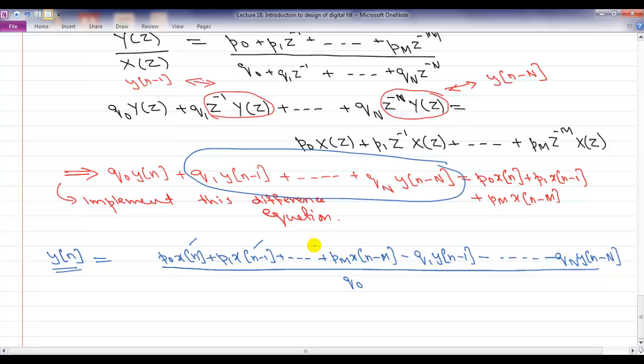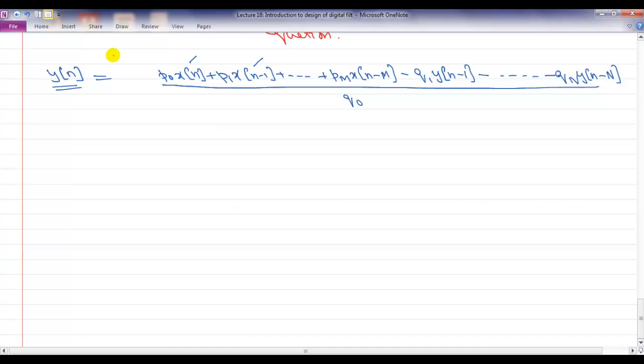So anytime you are given an IIR filter, you cannot implement it directly in hardware, but if an IIR filter has a z transform which is a rational function of z, then you use that to write a difference equation, and then you just implement that difference equation in hardware. So since I have just relied on arbitrary variables, I'll give a more concrete example just to help you guys out. Let's say that I was given a filter which had an impulse response given by the following.